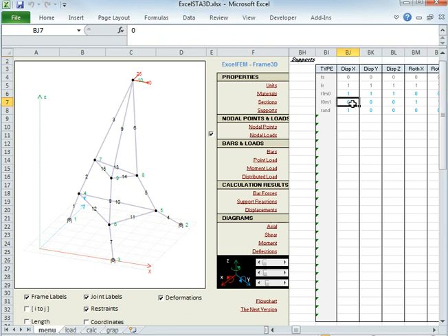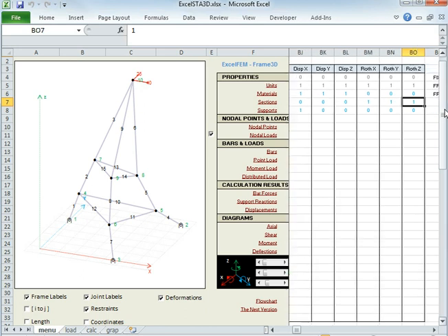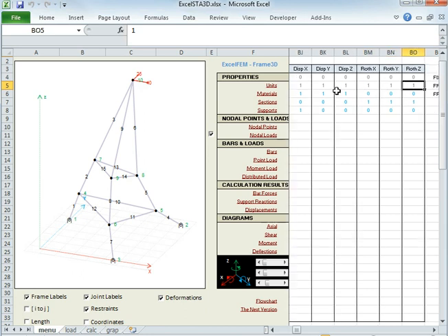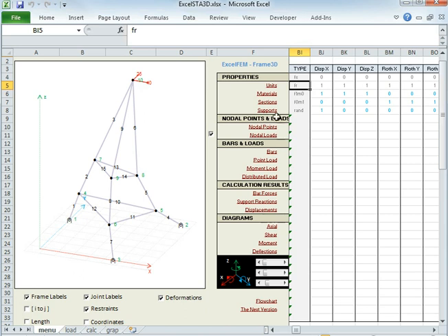This particular type means a pin support because it's going to block the displacements in the X, Y, and Z directions, but it's going to leave rotations free. There you go. And a normal beam-to-beam connection here, say between node 8 there, the normal connection at node 8, that's obviously free to move in any direction. So in fact that little symbol there, free, means it's free in X, Y, Z, and rotationally in the X, Y, Z rotational directions too. So we have support types as well.